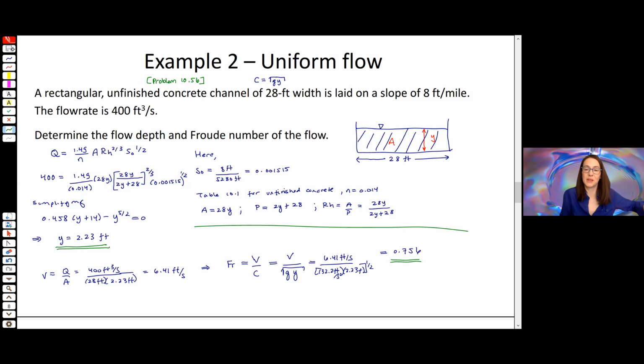A hydraulic jump is something that happens when the flow in the channel catches up to the wave speed, and then you can get basically stacking of depths. You get a bunch of waves stacked at one location because the wave and the channel flow are at the same rate, so fluid particles in the wave and in the channel below them are moving in the same location. That's when you can get a hydraulic jump. So indeed this is subcritical flow because it's less than 1.